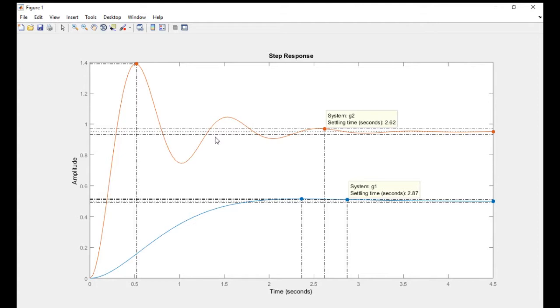So imagine the drone doing that kind of behavior. Certainly that is dangerous. And beyond it, it has the oscillatory behavior. It went up and then quickly went to its new position, but it had some oscillatory behavior, which lasted for about 2.5 seconds before it settled down. All right, so these are some of the things that we want to be able to extract from a system response curve.